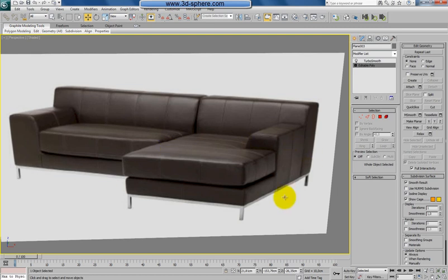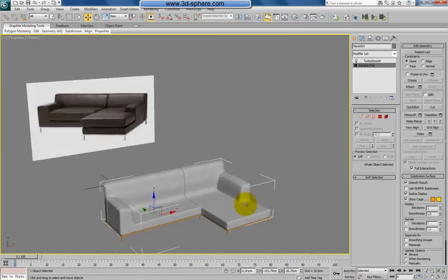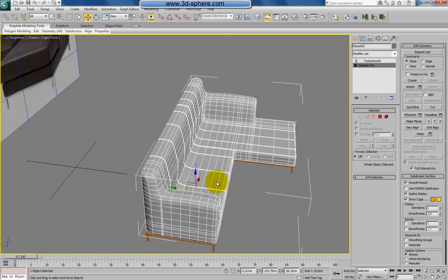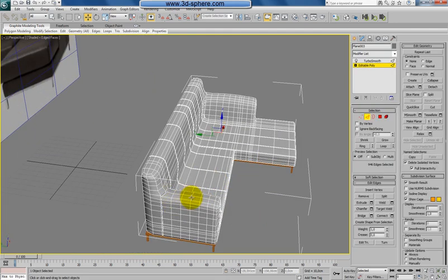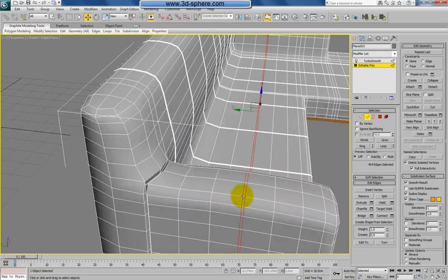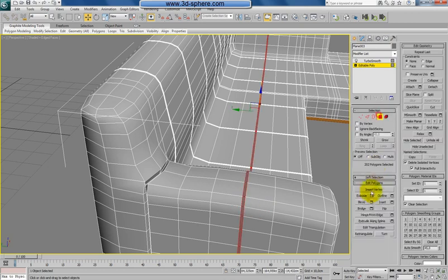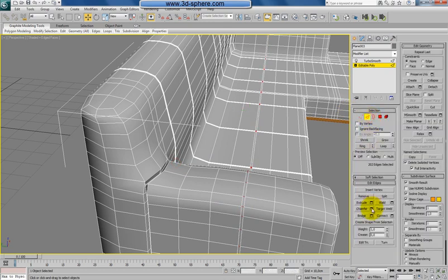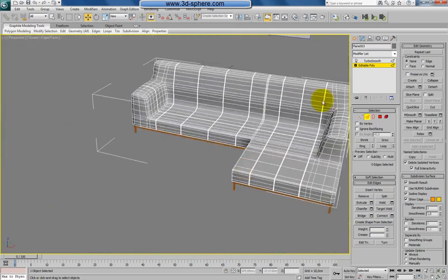Now, these ones here should be quite quick and easy. We'll just pick up one of them. Should be one in the middle, so let's go with this one. We'll just get loop. We'll do the chamfer trick because we still have the same values saved, so we just need to select this one, ring, control poly, extrude, okay, back here, connect, okay, extrude, okay, you see, very quickly.